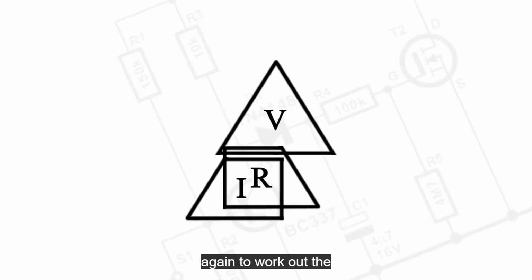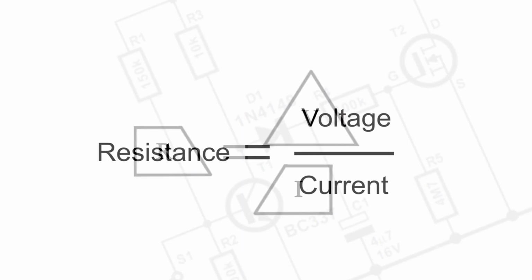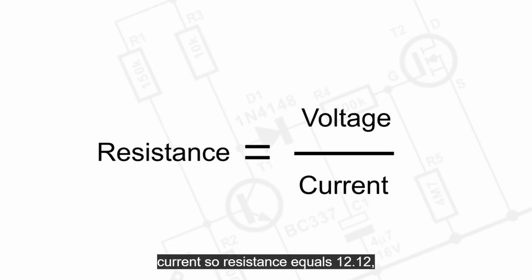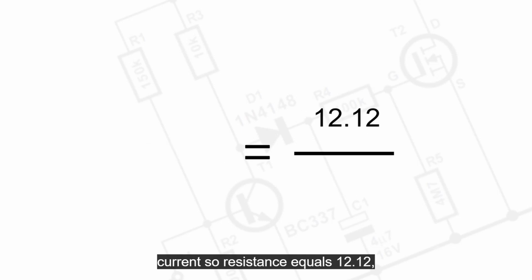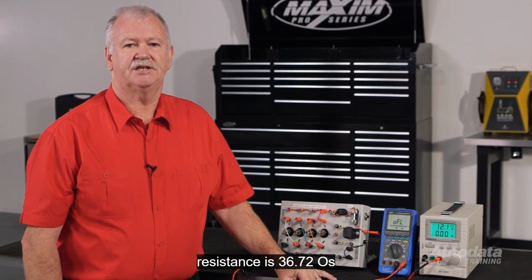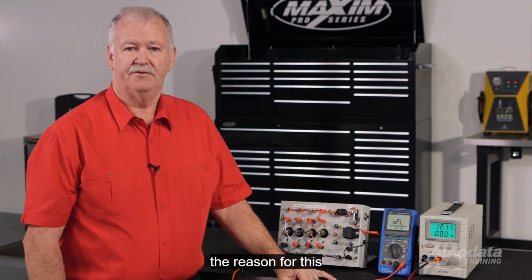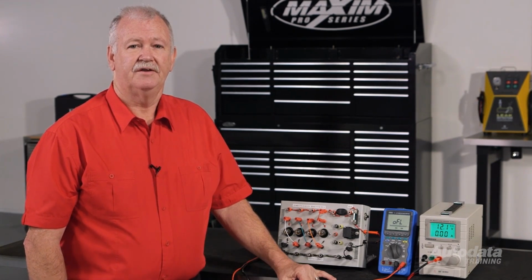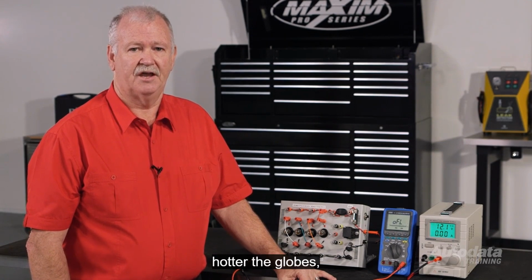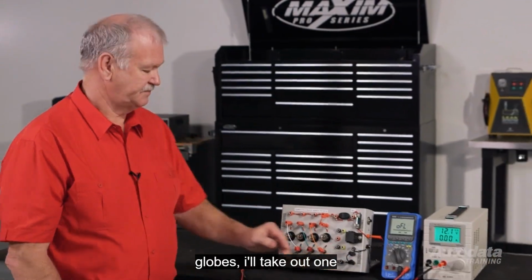We'll use Ohm's law again to work out the resistance using the supply voltage and our measured current. Resistance equals voltage divided by current. So resistance equals 12.12 divided by 0.33. Our resistance is 36.72 ohms. So the operating circuit resistance is 36.72 ohms. This is much higher than our first total resistance reading. The reason for this is the globes are hot. This affects resistance. The hotter the globes, the higher the resistance.